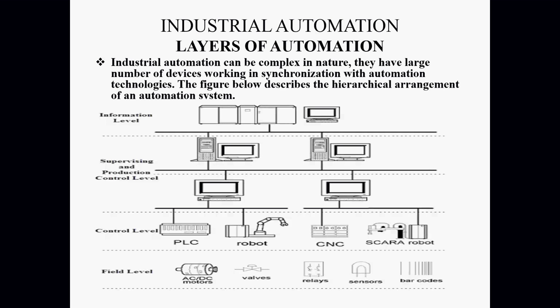Typically a SCADA system will have an engineering workstation and an operator workstation. Your engineering workstation is where you are going to engineer your project. Project being the graphic, the client, or the runtime, whatever you like to call it, that you're going to run. You create that in your engineering environment. So it will have the software and the licenses for creating your logic, for creating your SCADA graphic screens and everything. And the operator station is typically where you run runtime and logic and everything, right?